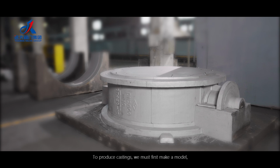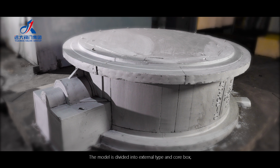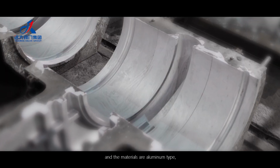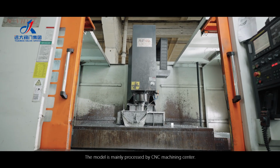To produce castings, we must first make a model, which is the mold used to form castings in the casting process. The model is divided into external type and core box, and the materials are aluminum type, wood type and iron type. The model is mainly processed by CNC Machining Center.